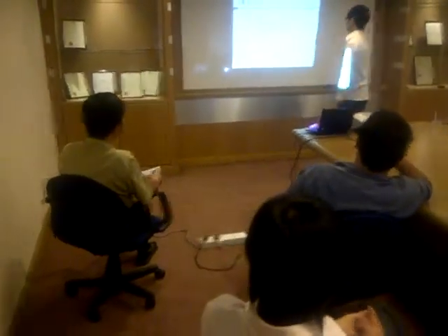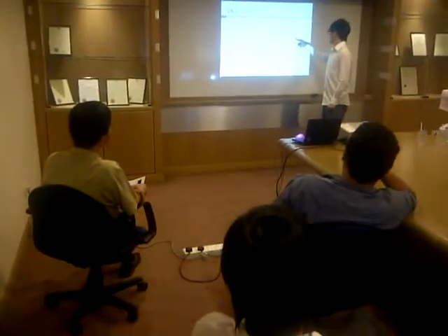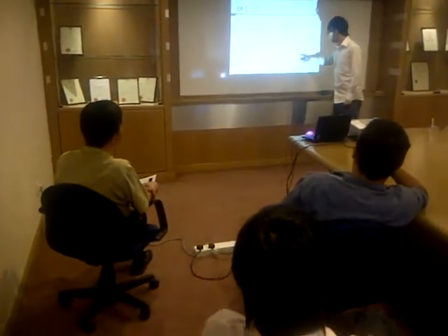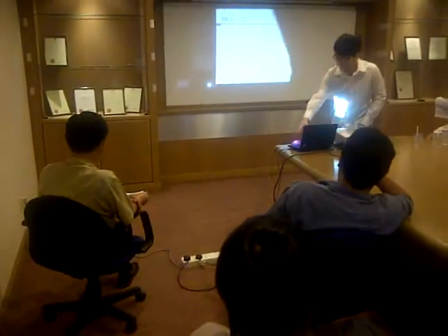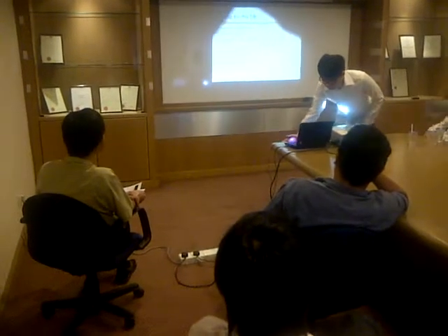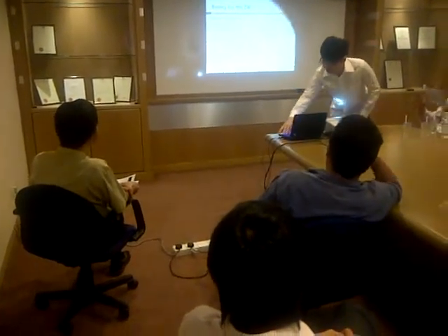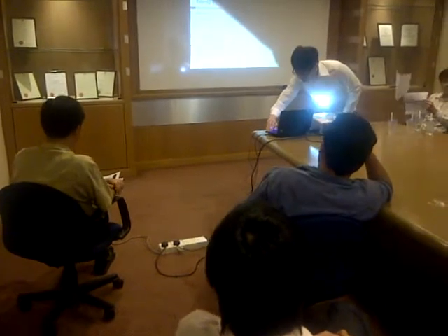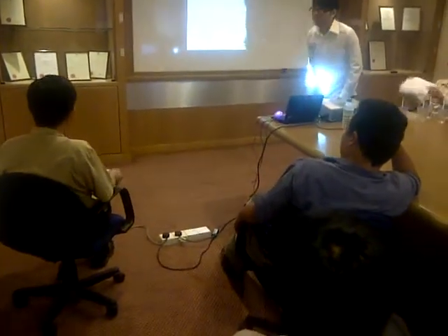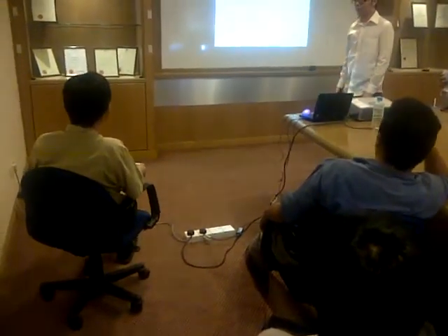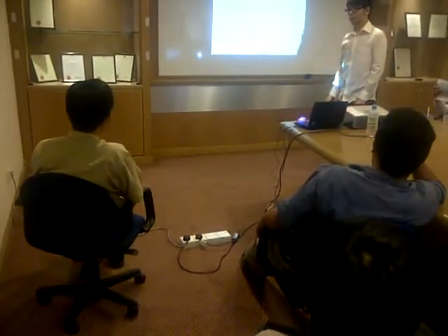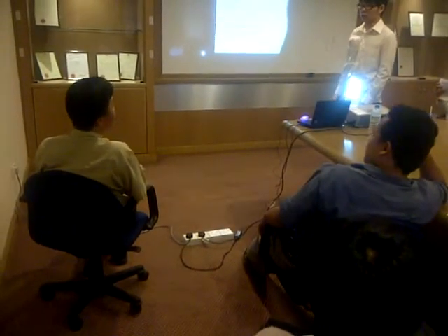Okay. And then this DB just supplies the switch socket outlet. They'll be the same for the RCD. Another thing, for the switch socket outlet, you assume 70% is used. I think it's on the high side.